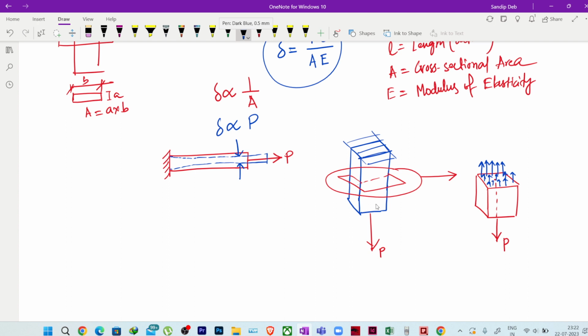Okay, in this cross section, the internal forces, or I would say reactions, to P, my applied load or applied force. So these reactions, if this is acting at the axis, or along the axis of this particular bar, in this case, this distribution of internal forces, which is opposite in nature to the load or to the force, will be uniform distribution.